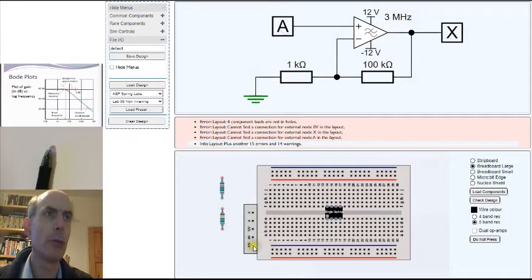And we've got to do something like the power supply as well. I could put the minus 12 volt power supply down here and just hook across to there. That would give me my minus 12 on pin 4 of my op-amp. My plus 12 could go across to here and down into power pin 7 to power the op-amp, and so on. Have a go at arranging things. As I say, it's good experience.